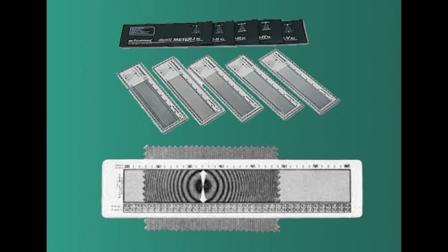It is like a scale with markings of the thread count, maybe 10s, 20s, 30s, 40s, like that. When it is placed over the fabric, the light rays form a pattern on the scale, and the corresponding thread number is noted in the center. And so, it can be placed on any fabric, even in the bolt, and the reading can be taken easily and more quickly.